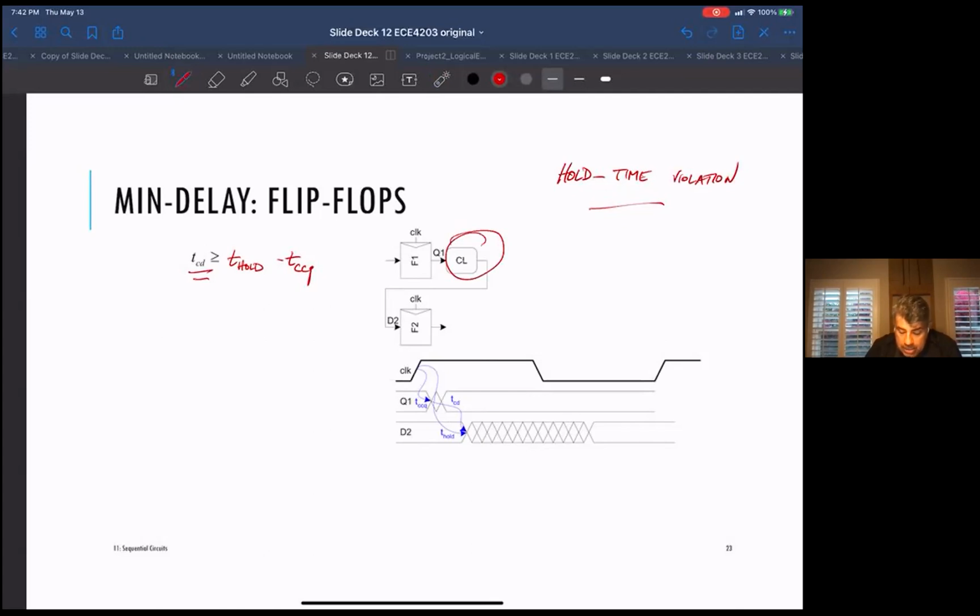Okay, and I can't emphasize this enough. This is really a situation where you'll see it. We haven't gone into testability, but if you get into chip design, you have these things called scan test in your chips, which are very commonly used. Long story short, you put all your flip-flops into this test mode where they get connected, just during the test mode, in a shift register type of sequence.